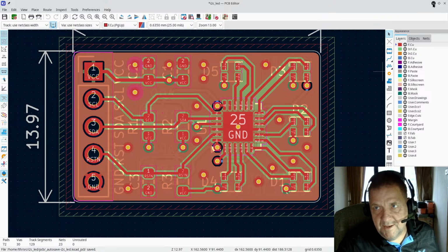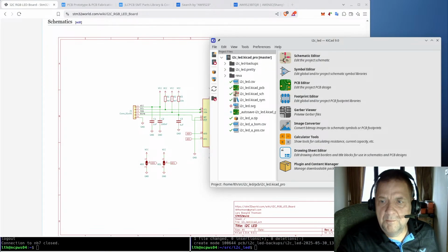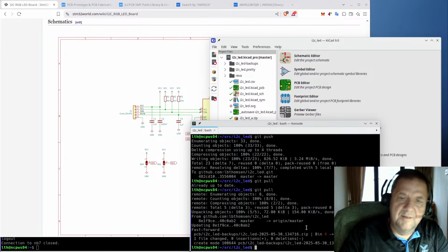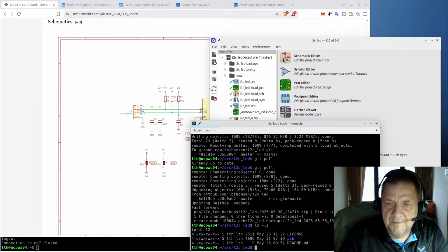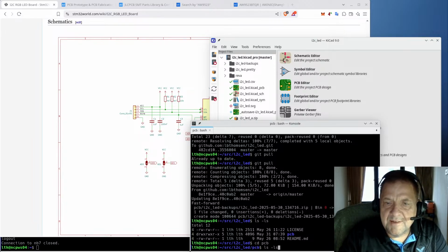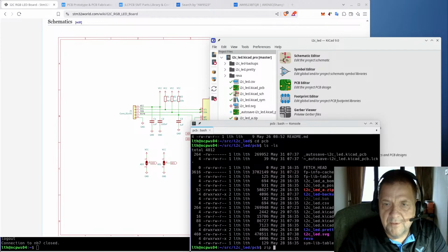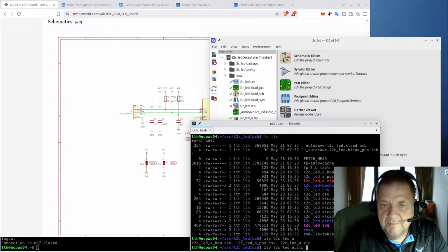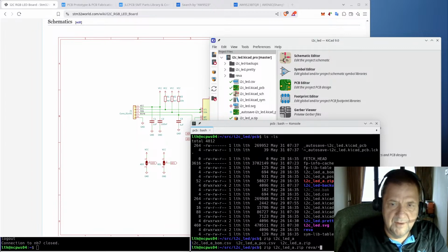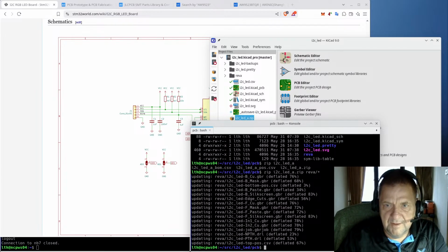Now, I don't care what you use, but by tradition, to keep track of the Gerber files, you basically create a zip file with them. So the first step I'll do is create a zip file called my project name zip, and I will take everything in that Rev A folder and put it into that zip file. So I'll have a zip file with all my Gerbers and all my drill files. JLC will figure out how to use it. So I create that zip file.